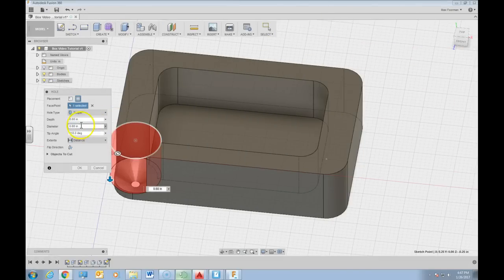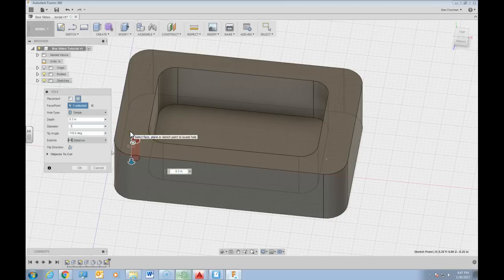So right now, how do we think we're going to adjust this? And also the depth that needs to go to, I'll have to look that up. I think I neglected to put that in on the drawing. Let me just type something in for right now. So depth, that is going to go to say 300 thousandths of an inch deep, just for right now. The diameter here then instead is going to be, alter this and see how the depth of that hole changed. Now when I type this in, 0.1248. That looks a lot better.